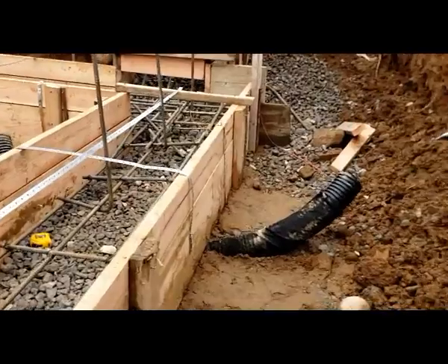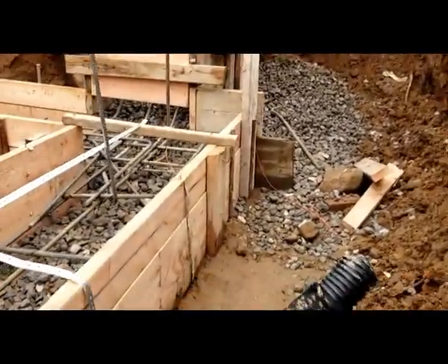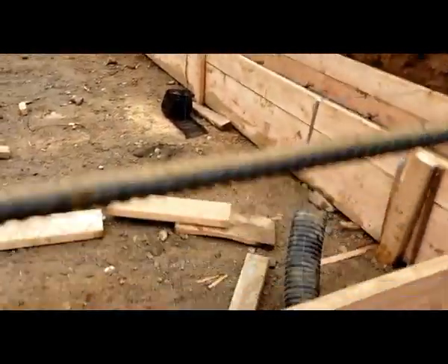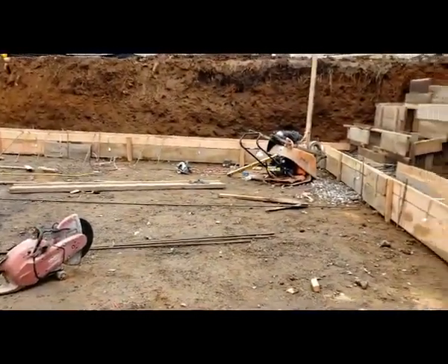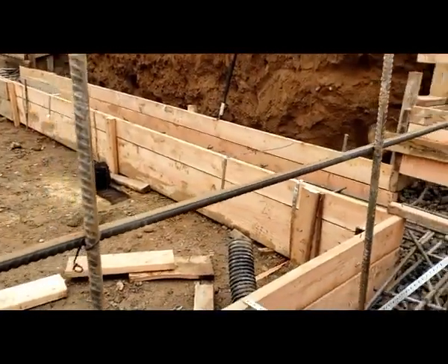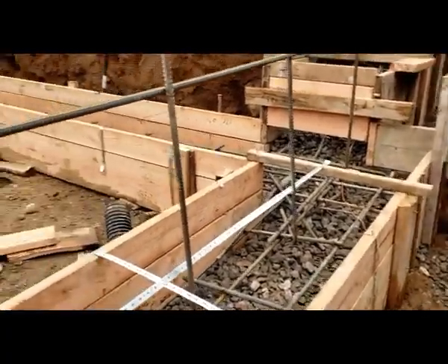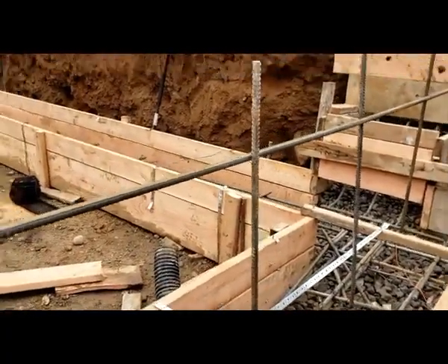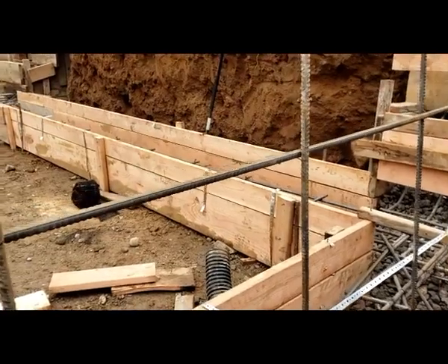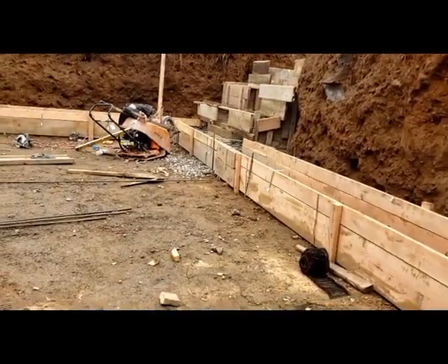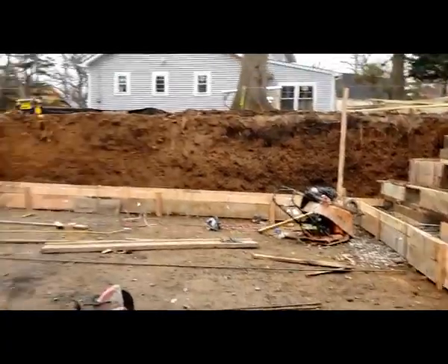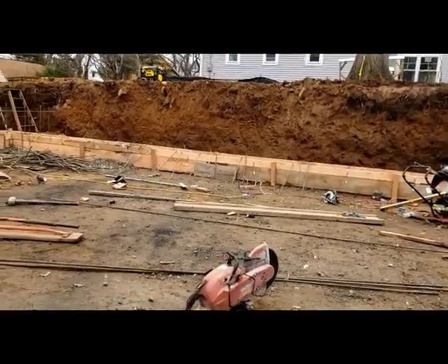Your backfill is nice stone and compaction. Here's a black corrugated pipe, and this is for the French drain, and the other side will get us to the sump pump. Now this is another important thing. Make sure you run these pipes under the footing so you don't compromise the footing. So usually, it goes by order. You put the stone, you compact, and before you run your steel, make sure you run your pipes, you compact again, and you run the steel.